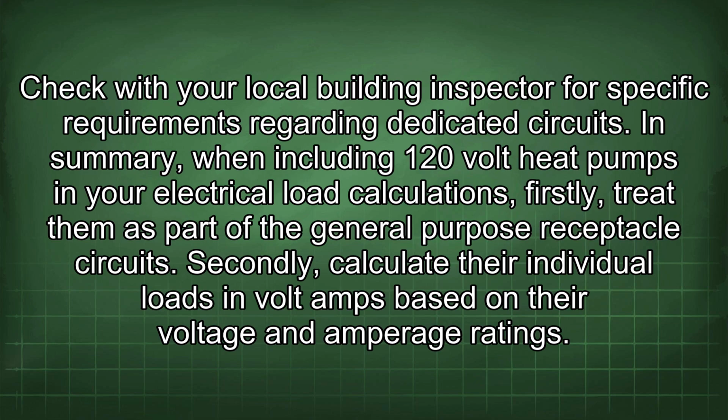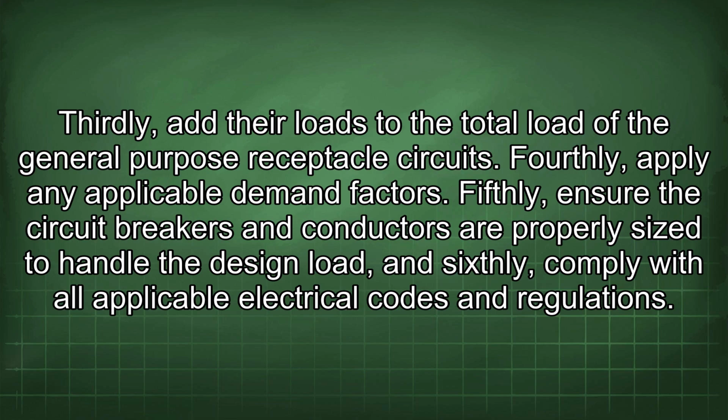In summary, when including 120-volt heat pumps in your electrical load calculations, firstly, treat them as part of the general-purpose receptacle circuits. Secondly, calculate their individual loads in volt-amps based on their voltage and amperage ratings. Thirdly, add their loads to the total load of the general-purpose receptacle circuit. Fourthly, apply any applicable demand factors. Fifthly, ensure the circuit breakers and conductors are properly sized to handle the design load. And sixthly, comply with all applicable electrical codes and regulations.